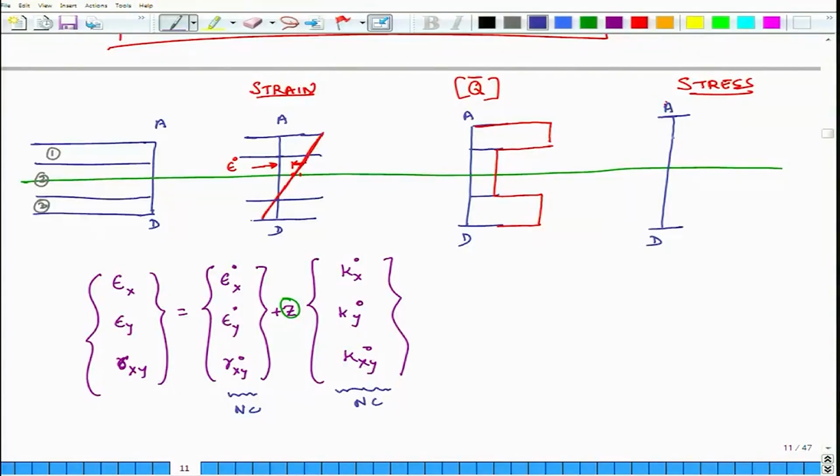So, the stress distribution or the stress function along the thickness of the plate. Suppose these are 3 layers. The stress could vary something like this within a layer, then because Q bar is changing and Q bar is becoming very small, it becomes very small, and then again it changes linearly over the second layer, and then again Q bar becomes large and again it changes linearly.